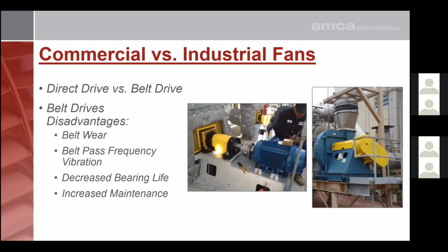Belt drives also require tension to operate, and that belt tension or belt pull applies additional load on the fan and motor bearings, and that can decrease the life of those bearings.